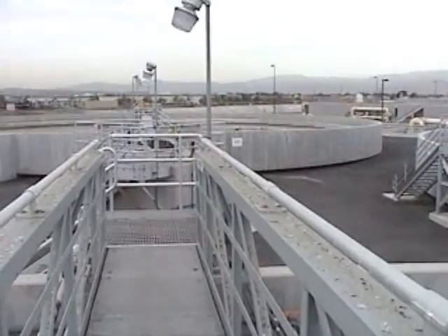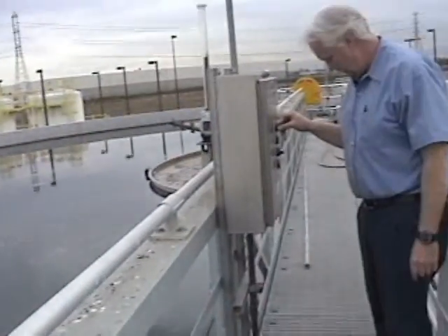One of the problems that you can have though is if the skimmer is stuck or something like that, or else, what we've seen the most frequently, is the scum pump station is full. Right now you can tell that there's no problems with the scum removal system because this liquid is flowing. I'm going to stop it right here. But see how the trough is flowing? If the scum pumps were not doing their job, that would be standing water right there. So that's how you can tell that the scum removal system isn't working.